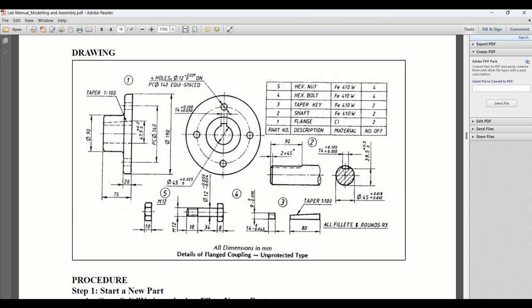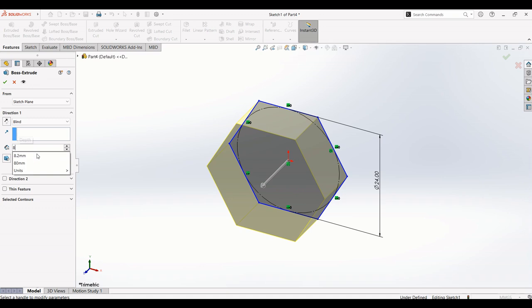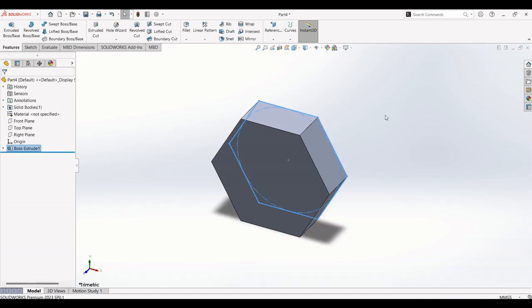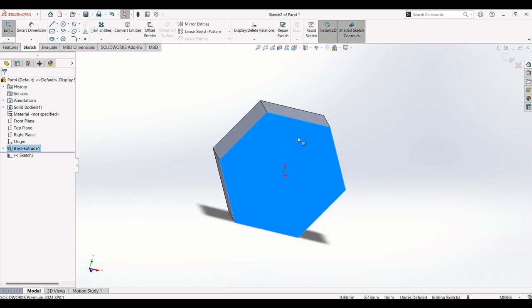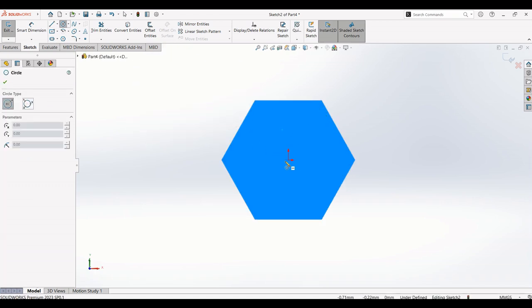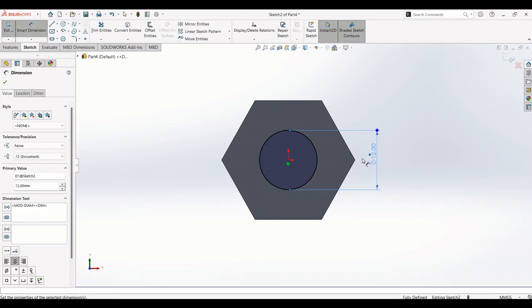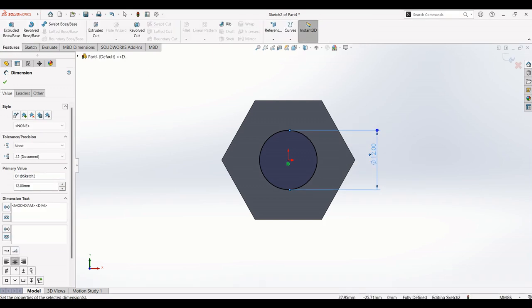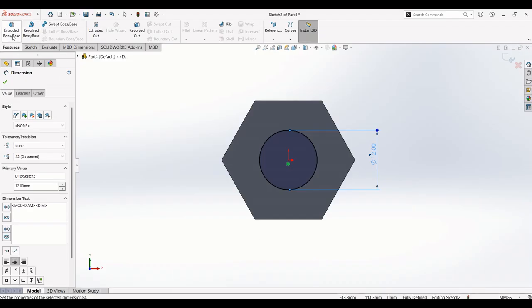It should be extruded for a length of 8 mm. So extrude 8, select OK. Now select the center surface, sketch. Take a circle. The diameter of the circle is 12, and the extrude length is, check it, 34 plus 18, which is 52.